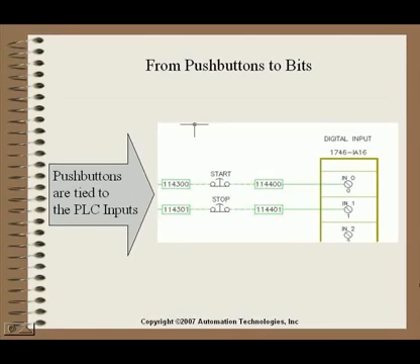So what's the difference between the PLC and the regular hardwired option? With hardwired, you saw we take our push buttons directly to a relay, and it acts directly upon that relay. With the PLC, we have our start button, and it comes into an input card. It's wired directly into cards that interface directly to the processor through a rack or some other means.